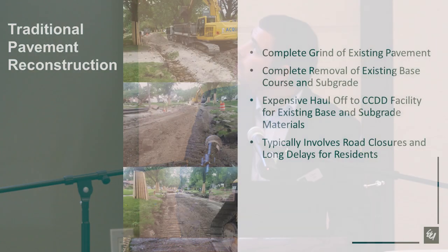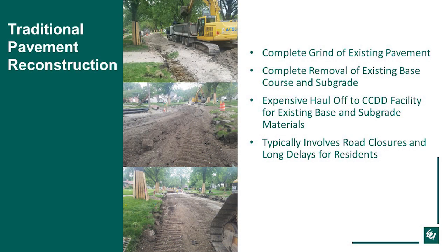So based on the information that was discussed earlier, if we determine that pavement reconstruction is the correct route to go down, then you'll have to completely grind off the existing pavement, and then you'll typically have to remove and replace the existing base course, proof roll the subgrade, and maybe make repairs to the subgrade. Obviously, this is typically a very lengthy project. It takes a long time for the contractor to remove all the material and get it all graded out, and it has a great impact on the residents.